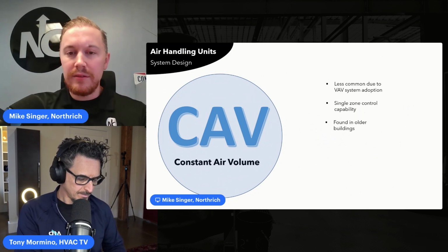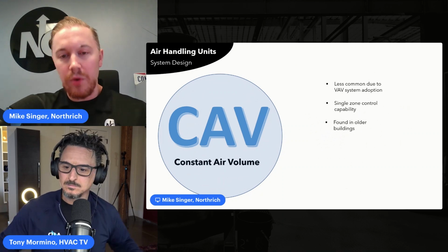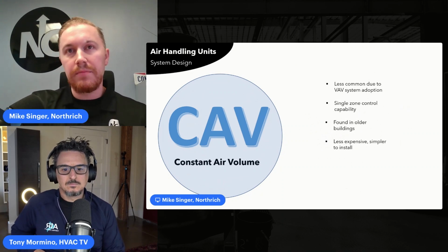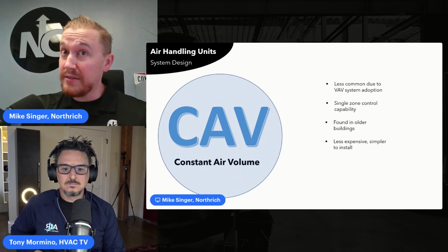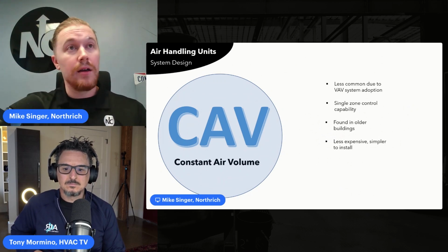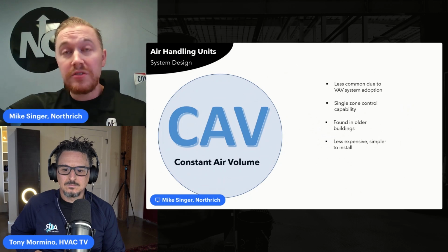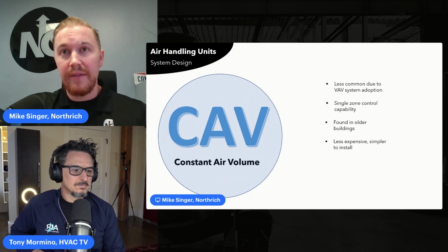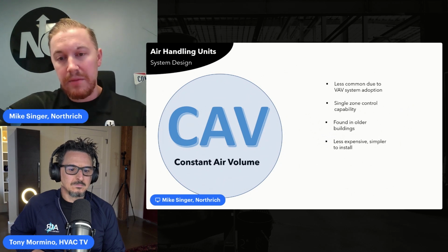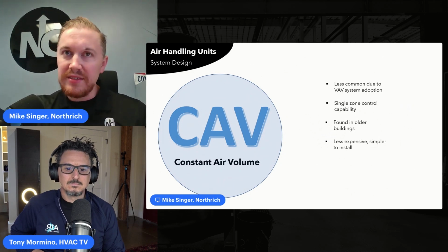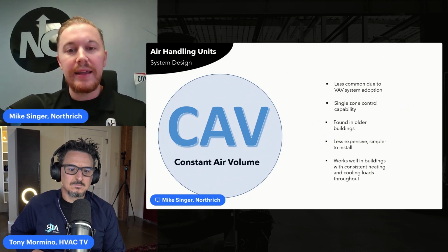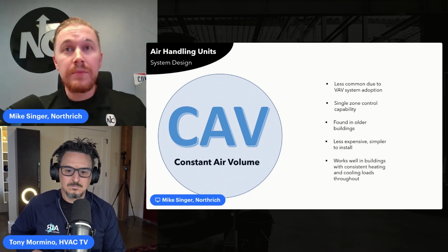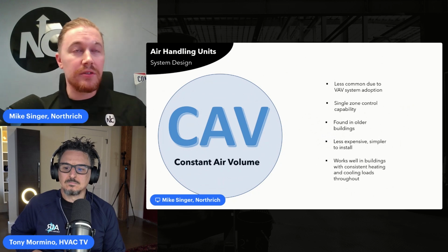So typically we're going to find these in older buildings where we haven't seen upgrades into a VAV type of system. They're less expensive. We don't have a VFD on the fan motors. We don't have all of the sensors we would be required to have in a VAV system, and we don't have VAV boxes. So it's going to be a simple install and a pretty inexpensive first cost. And they actually work very well in buildings that have consistent heating loads and cooling loads throughout.